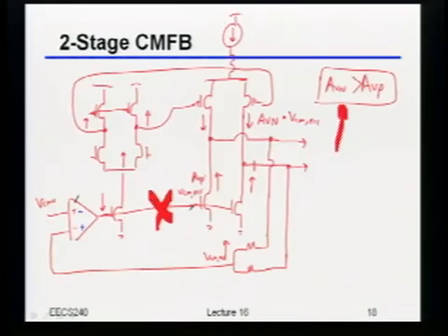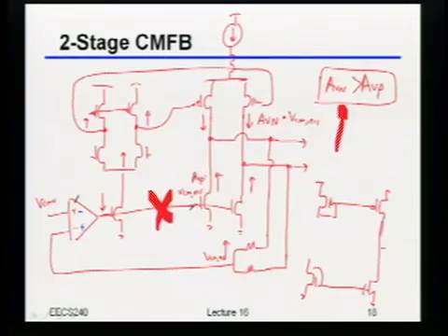Because the first stage will fix the second stage common mode, right? Says who? These are both high impedance. So what if there's just an ever so small mismatch between, you know, this mirroring ratio or that mirroring ratio? If this is a high gain stage, who knows what the common mode is, right? Because remember, although in Spice it's usually perfectly happy to tell you that this works, anytime you do something like that, you do not know where that common mode is actually sitting.